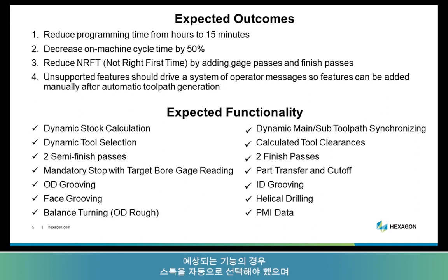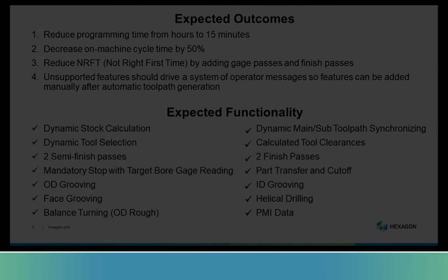For their expected functionality, we had to automatically select their stock. We needed to synchronize the main and sub-spindle toolpaths and part transfers. Everything had to be automated: OD grooving, ID grooving, face grooving, helical drilling, balance turning. And we introduced something brand new, PMI data.